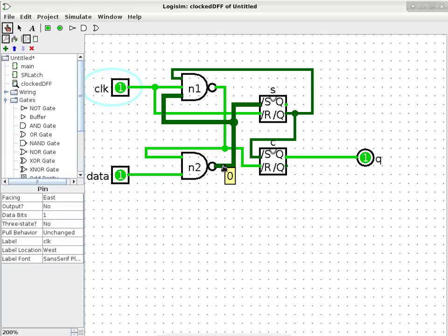And the third input of N1 is also going to be a 1. But because the output of the SR latch is outputting a 0, N1 itself will continue to output a 1. So that part does not change. And as a result, there's no change to the C SR latch. The C SR latch will continue to see a 0 from the /S pin and a 1 from the /R pin, so it will still maintain its state. It's not going to turn into a 0. We'll do it just to make sure. And that's exactly what I said.